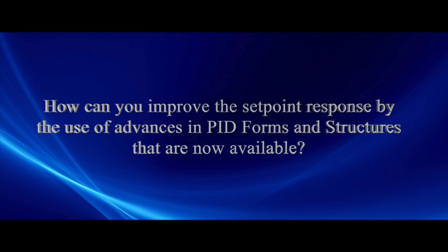If the rate time is larger, or even approaches the reset time, in the ISA standard form, you're going to get into really severe oscillations, just due to the modes. There isn't this built-in interaction effect to help protect you against having too much rate setting. So a common problem is people literally go from the series to the ISA standard form with too much rate action, and now they're oscillating like crazy, very fast oscillations due to this rate action.